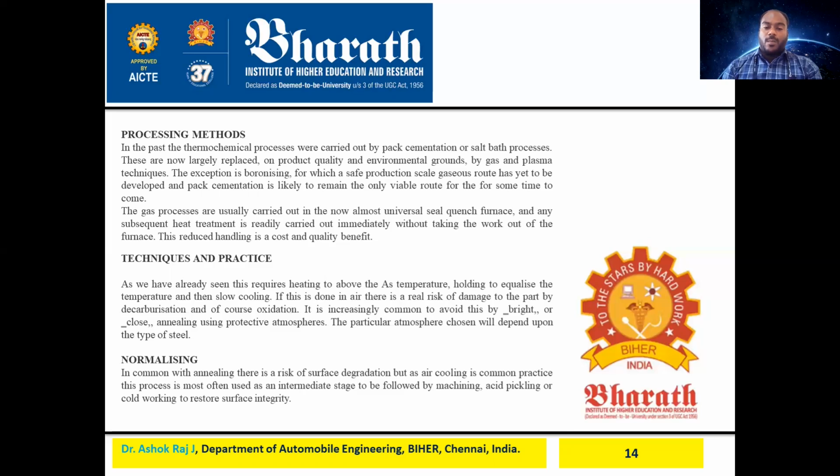Normalizing. In common with annealing, there is a risk of surface degradation, but as air cooling is common practice, this process is most often used as an intermediate stage, followed by machining and acid pickling or cold working to restore surface integrity.